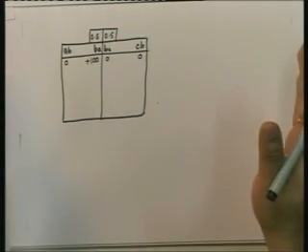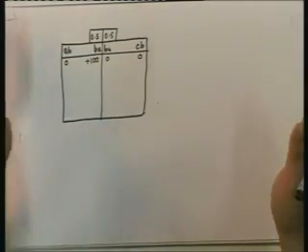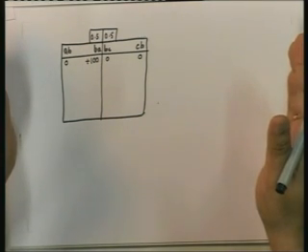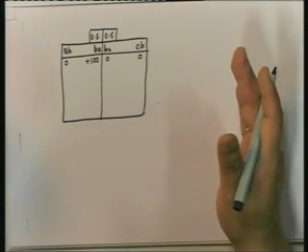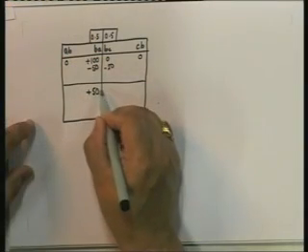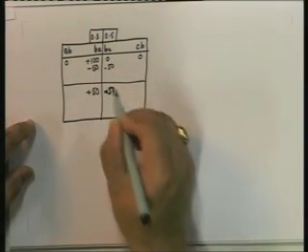Because why? My whole goal here is to actually find out C1, which relates the bending moment at B to the fixed end moment at BA. Okay. So first is going to be distribution minus 50, minus 50, and look at this, nothing is going to happen here because no carryover there. It's already 3 by 4 modified. So what we get is plus 50, minus 50.